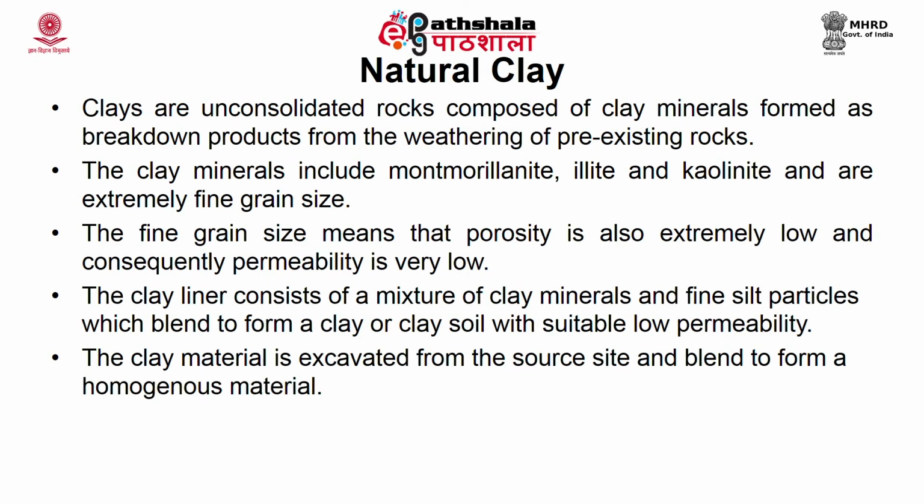Now, where do you get this clay material? In a previous module I told you the availability of material should also be considered as a criterion for site selection. So, the clay material can be excavated or trenched out from the site where your landfill is to be constructed, or it can also be brought from nearby areas.